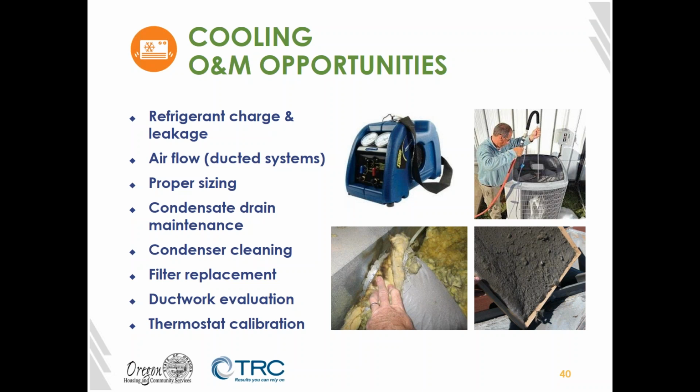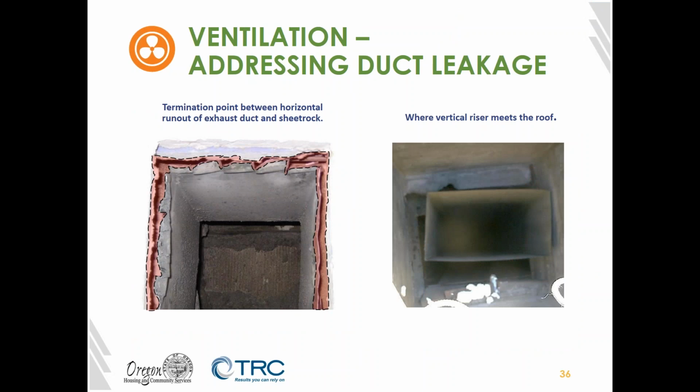Yeah, so if we go back to that slide, I mean, you can look at this. If you pop the fan off, in this case of the roof, or you pop the register off of the wall in this case, a visual inspection would be sufficient for you to say, oh my Lord, I probably have a really leaky system. And then come in here and seal this duct.